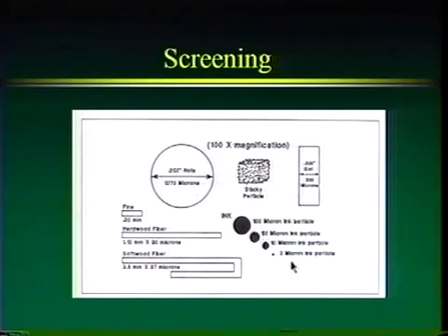Now, this slot and this hole are going to remove large debris very easily, like big pieces of plastic or unpulped 5 millimeter wide fibers. What neither of these screening barriers will remove is ink particles. And you can see ink particles could be 2 microns to 100 microns as an example. And you can easily visualize that they are going to pass through these openings.